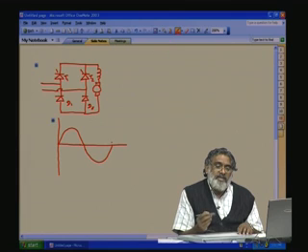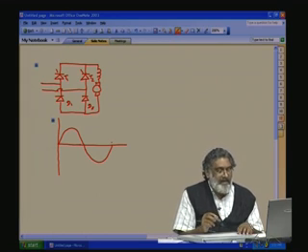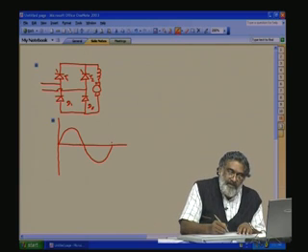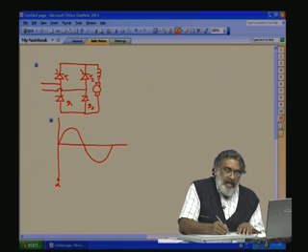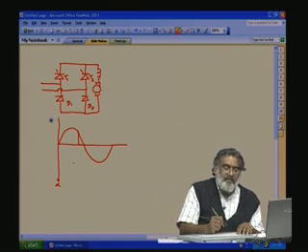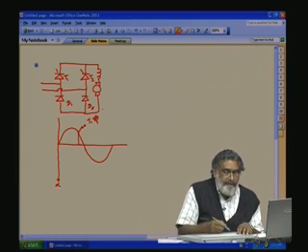Now, is it possible for us to make phi negative, or the current leading with respect to the input mains? Let us see a waveform like this. We are always firing at alpha equal to 0. Let us say the firing is with respect to this one, and we are turning off here. This is the turning off portion, the forced commutation, T1 off. So, what will happen?